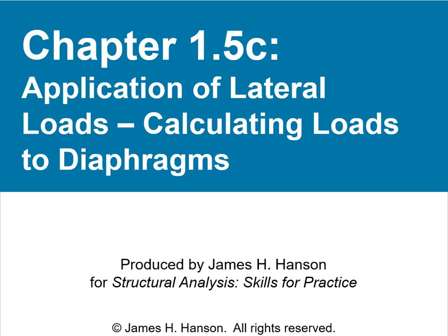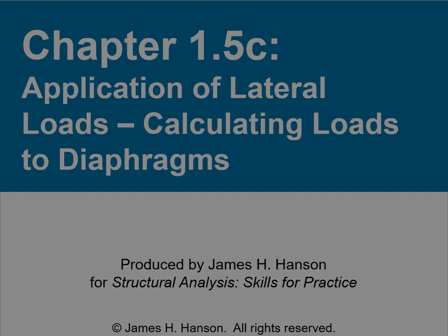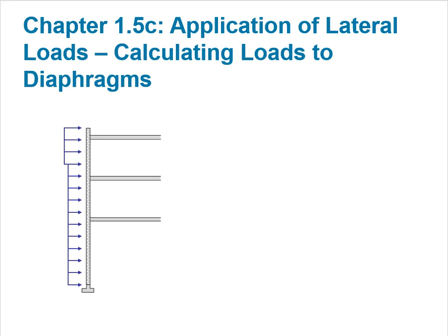Now that we have discussed load path for lateral loads and have laid out a process for analysis, let's take a closer look at how to calculate the load that gathers at each diaphragm. Pressure acts on the wall, and as we discussed in a previous video, the wall is supported laterally by the foundation and the diaphragms. This is a sketch of what is actually happening.